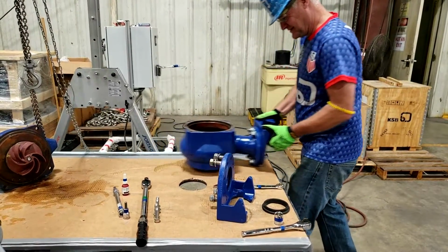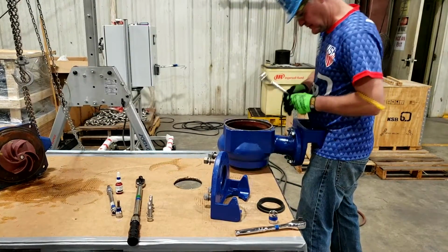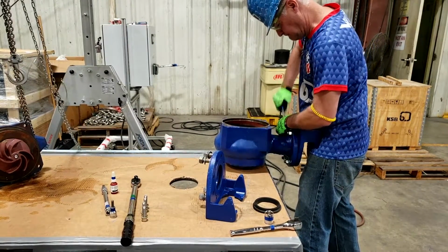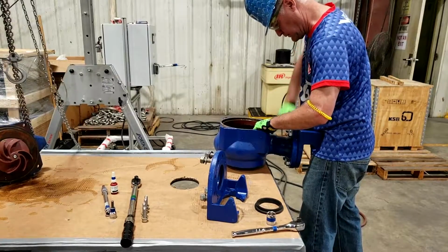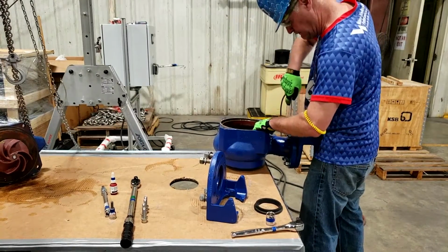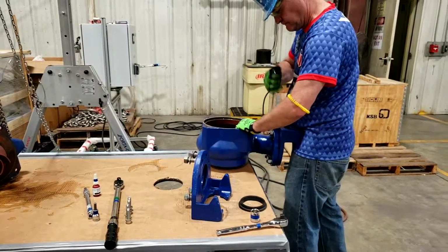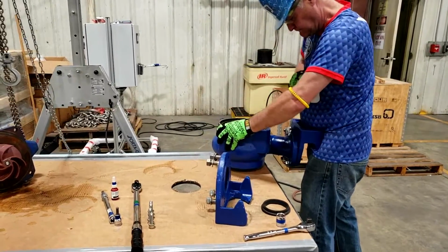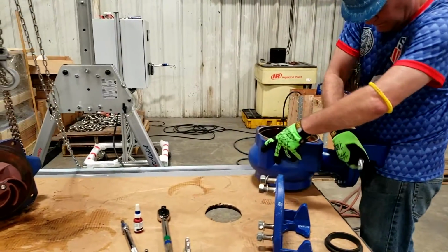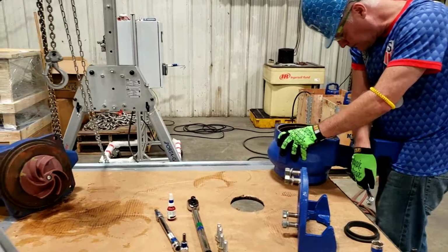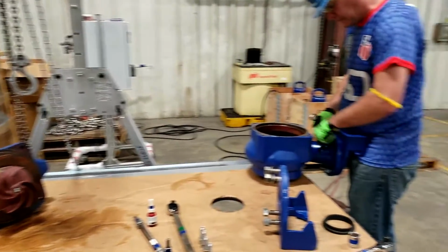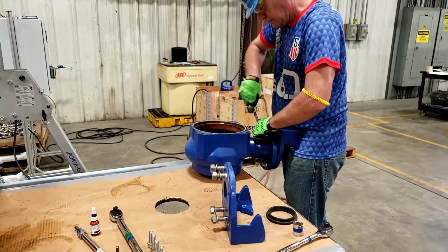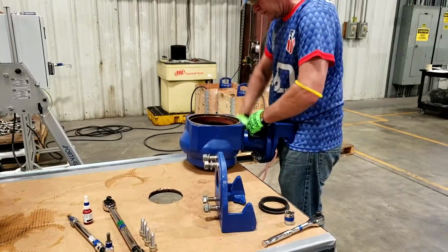KSB Pump Maintenance Event, Task 10, Volute servicing. You may slide the volute, but this must be done over the table. You cannot carry the volute off the table to move it to a different location on the table. Remove the guide claw by removing the four 24mm bolts, nuts, and washers using the 24mm socket and or 24mm combination wrench.